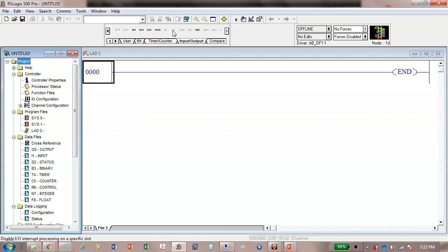If you save it to your flash drive, or your hard drive, or a network drive on your computer, it will ask you for a name. In RSLogix 5000, you enter the name first, and then you select the CPU. In the TIA Portal, you enter a name for the program first, and then you select the CPU. So it's kind of a little backwards on here.